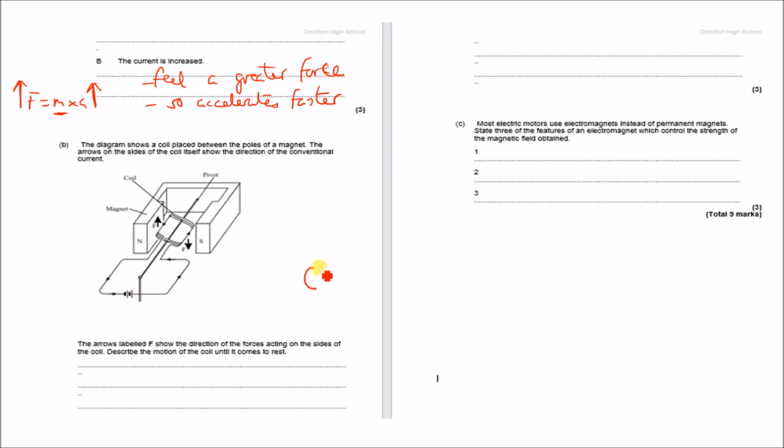Remember, normally you have a split ring that looks like this, and then that part is connected to the coil. And when this is connected to the positive and this is connected to the negative, it causes it to spin. Then when it gets to the half turn here, there is no connection with the positive and there is no connection with the negative, so the current comes off, and then as it spins round again, this part is reconnected with the positive and negative, and this causes it to spin 360 degrees. So you will only get this with a split ring commutator.